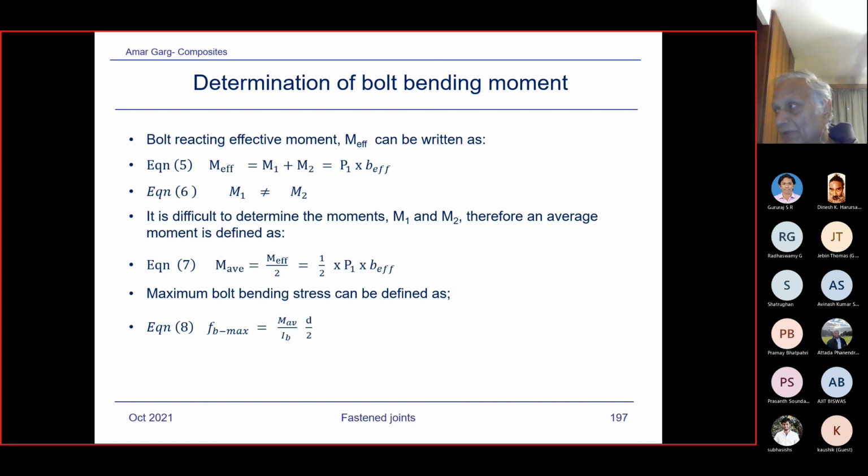But if you have ribs to skins, there may not be any washer, just the fastener and the collar. These collars already come with the washer. Normally nuts have the washer separately, but collars, like Hi-Lok fasteners, come with the washers automatically, so you don't use separate washers on those.